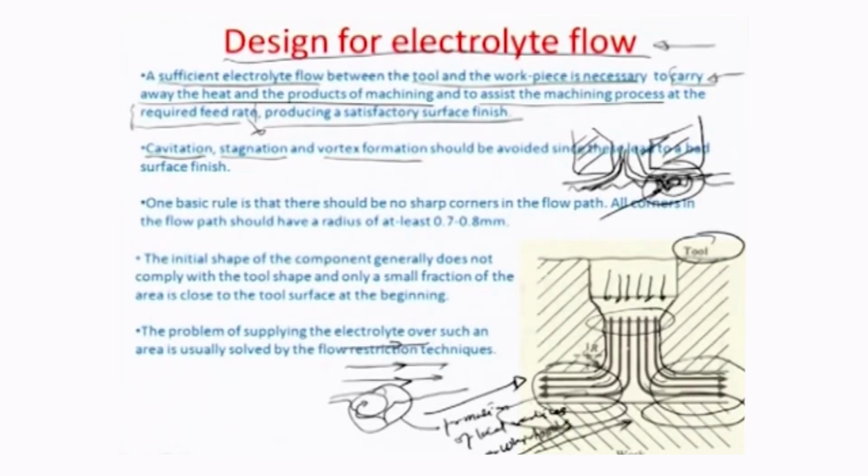Well, this can be dangerous to the ECM process, because number one, the local conductivity here is really a function of the amount of debris which is coming into this so called local whirlpool. We can assume that the debris gets confined here in this particular zone, it does not get moved ahead. The remaining debris which is generated from, let us say for example this surface or the other surfaces here would get carried away, but this local debris formation here does not go ahead anymore. Okay. So, there is a change in conductivity, there is a change in machining rate, there is a change in so many parameters which are associated with this vortex formation.